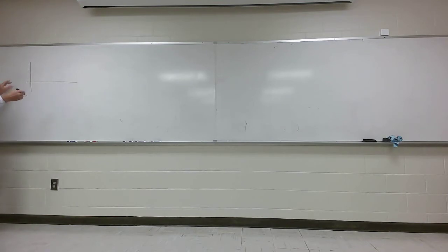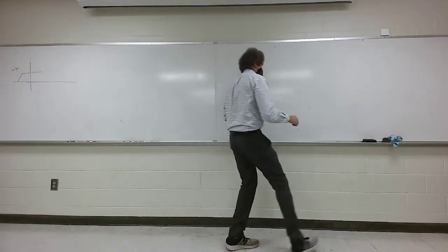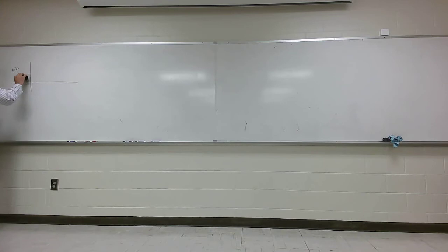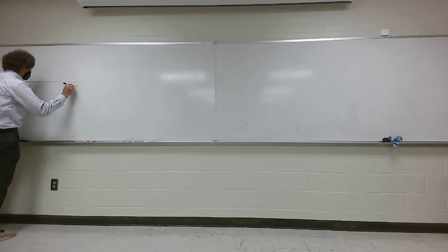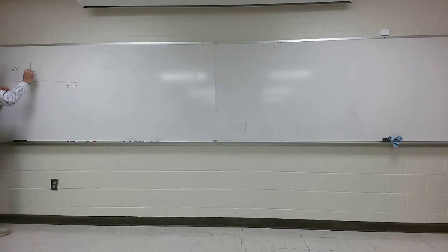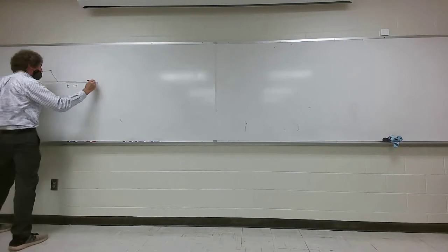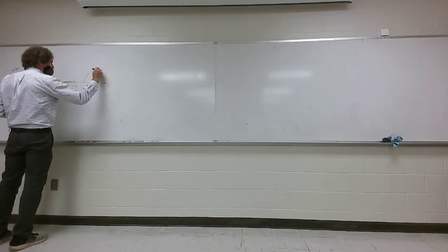So what affects these? We have to talk about the mathematics of the digital signal and the frequency components of it. In general, when you have V of t, you're going to have a pulse that has a rise. I don't like doing it this way, but I'll do it his way. If this is the time axis here, when we talk about digital signals, it'll have a rise time, it'll have a time where it's on, it'll have a decay time, and then the thing will repeat itself as such.